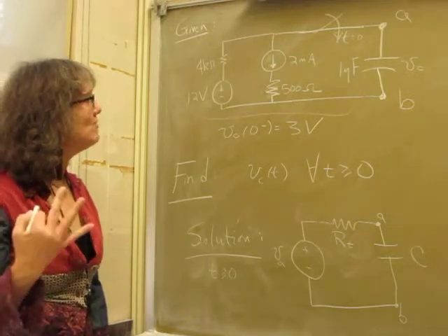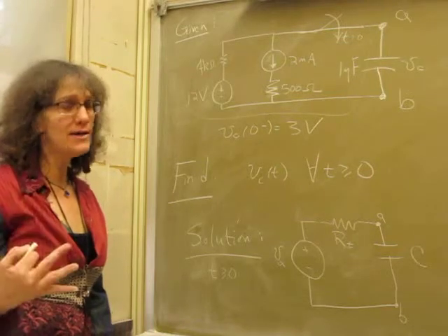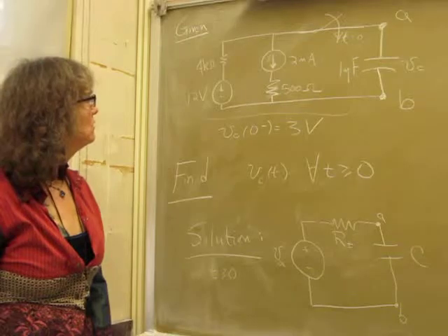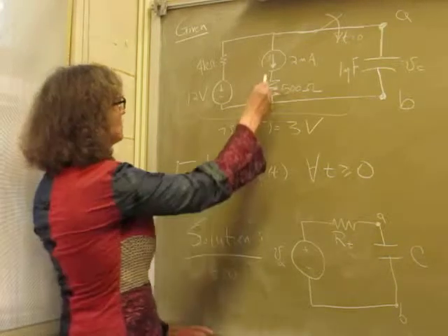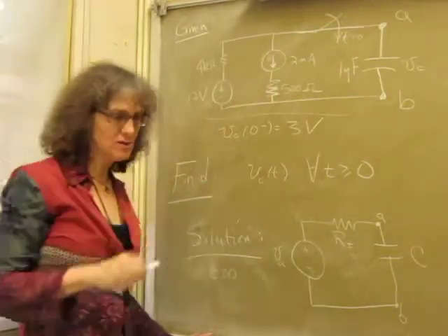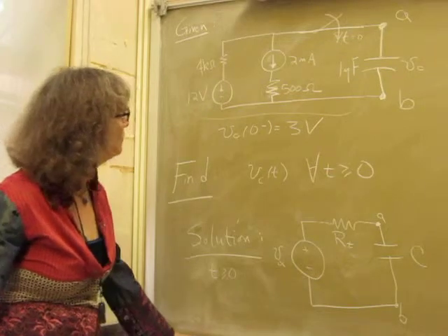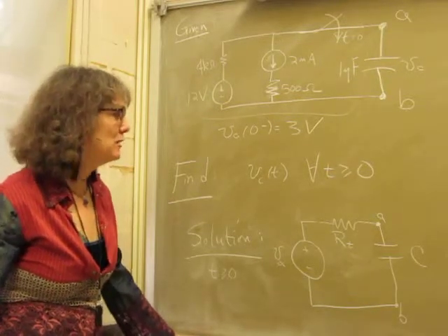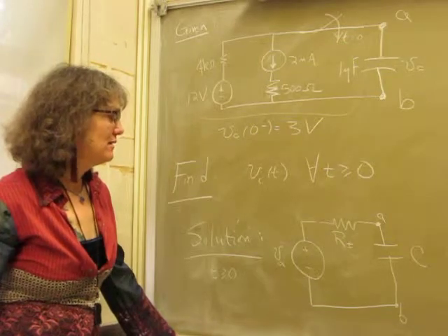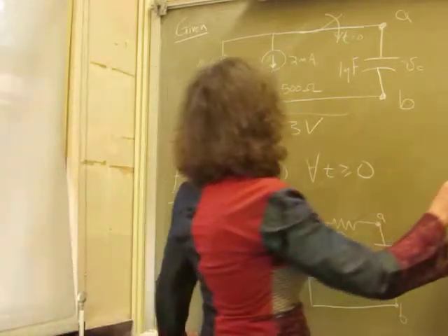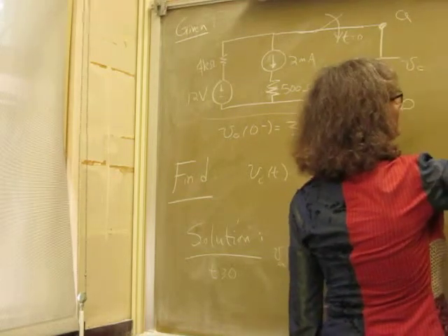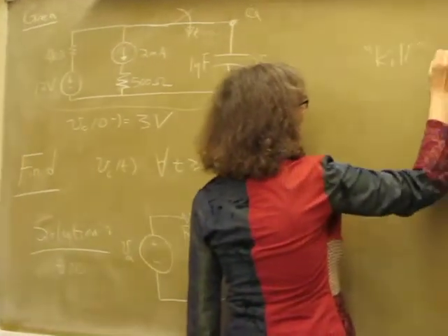If you have a circuit that only has independent sources, then you can find the Thevenin resistance by killing those sources. I know, I hate that word. It's not very nonviolent. By deactivating them. Anyway, that's such an easy word. So kill them. Kill them all.